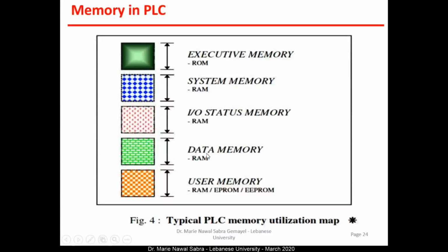I can have data, and these are erased when the PLC turns off unless I have a backup battery, so that if the current runs out and comes back, especially in our country where we have current regularly running off, the machine doesn't start from zero state, it continues from where it was. We need a battery backup for the values that are saved in the RAM.